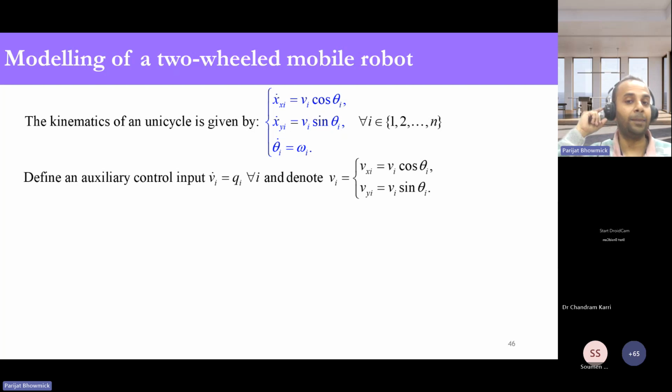We cannot directly apply the cooperative control law that we have learned because it's an NI cooperative control law. If we have to apply the NI principle, then the system must be LTI, because so far we haven't learned the nonlinear negative imaginary theory. So everybody is about to be very afraid: are we going to be stuck? No, actually here we are just going to apply one hack. Ultimately we would be proposing a two-loop control scheme where the inner loop would be a feedback linearizing control scheme.